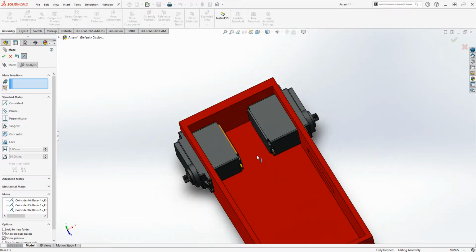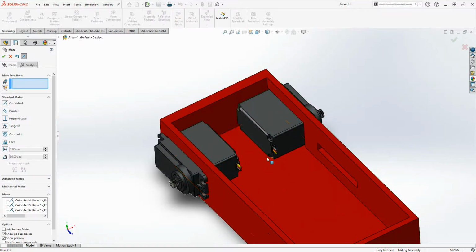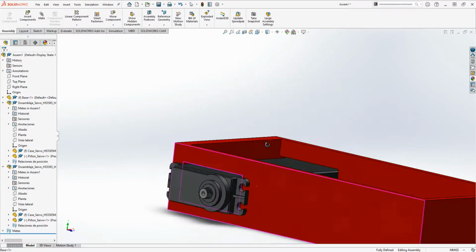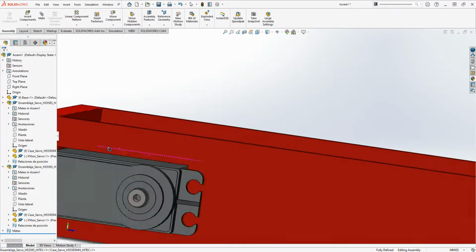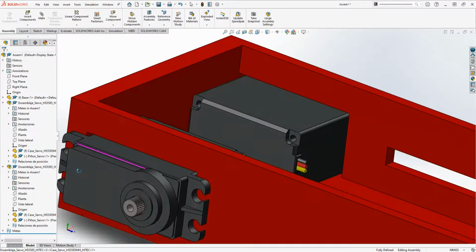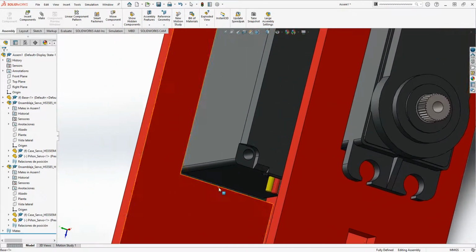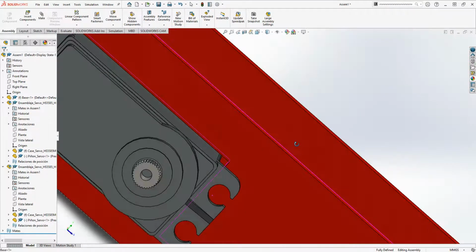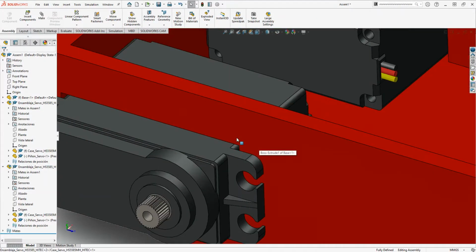You can see where servo motors normally would have a ground, power, and signal wire, the signal wire being what controls it, power giving it actual energy, and the ground wire, which is all part of basic circuits. It would be very important to have those pointing outwards and having room for them this way. We can all imagine that it really wouldn't work if I tried to put those wires on this side, right? They would bump into something. They want that free space in order to move back to the rest of your circuitry.